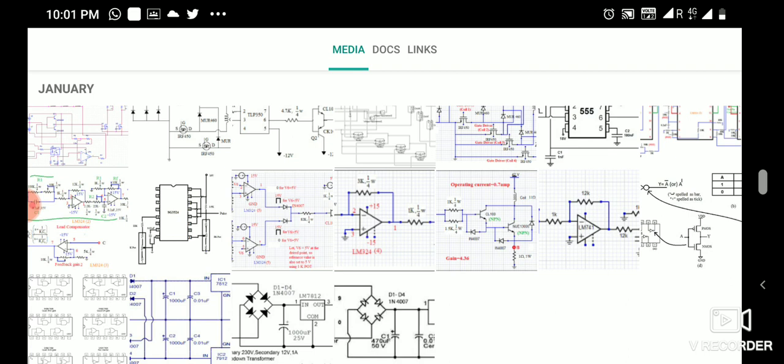Now we will test the circuit with the associated circuits and take the waveforms. If it is stably levitated, we will get a stable current of 0.9 ampere. The transistor will provide this. Otherwise, the system is actually an unstable system, so either it will touch the coil or it will fall down. When everything works properly and the controller works properly, the system will be stable.